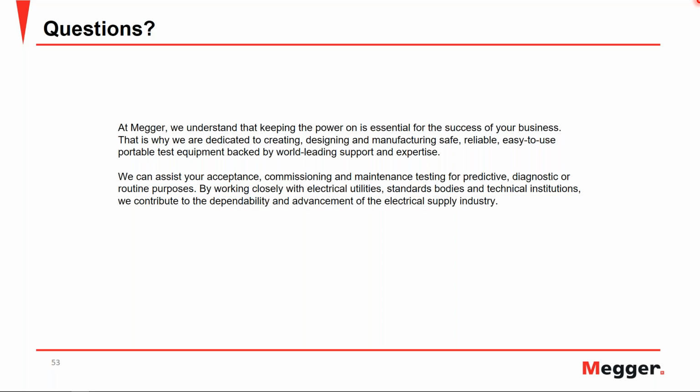And if you are talking in general about insulation assessment, there are other tests available like DC insulation, PD, high pot. On cables, you do VLF testing. So there are a number of other tests available that can be used for insulation assessment.